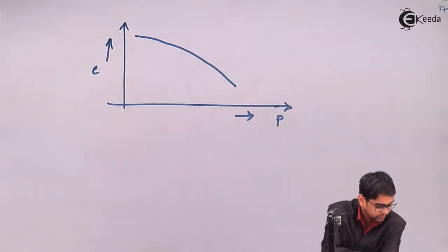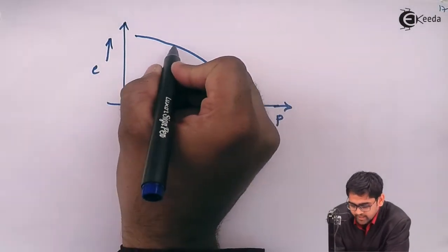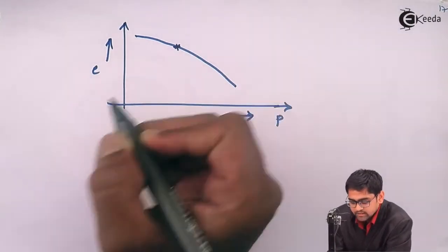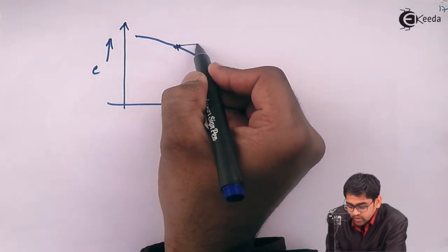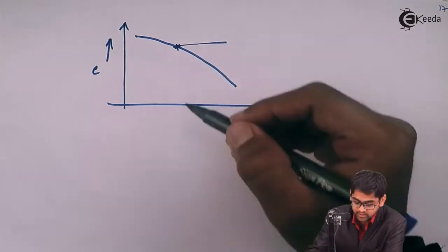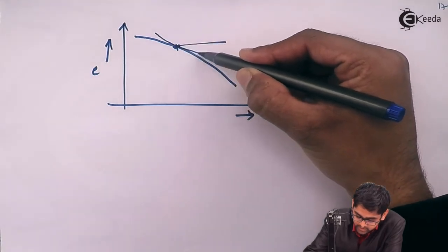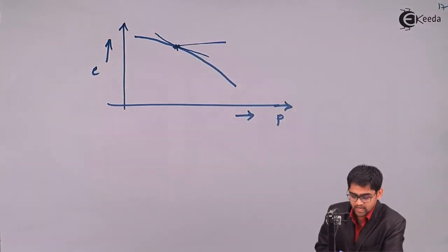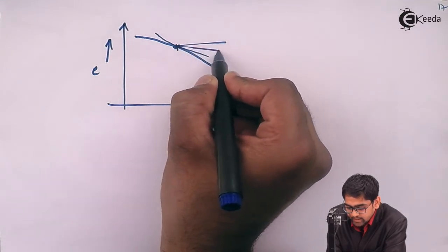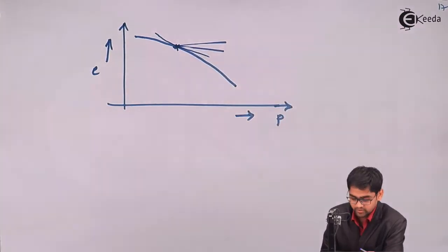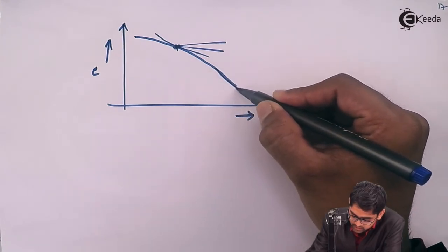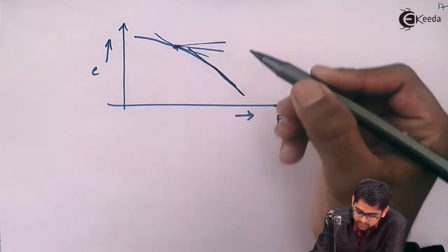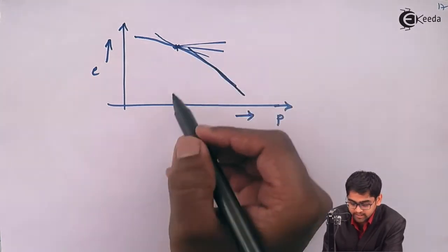By that procedure, you find the point which has the maximum curvature or the minimum radius, and from that you draw one horizontal straight line and a tangent line to the curve. You bisect the angle made by the tangent with the horizontal, and extend the straight line part backward, and it meets this angle bisector at this point.